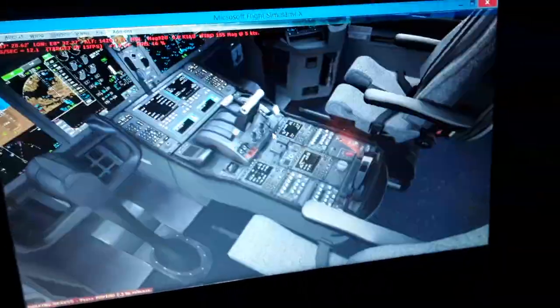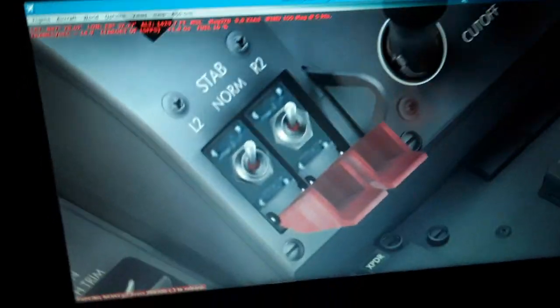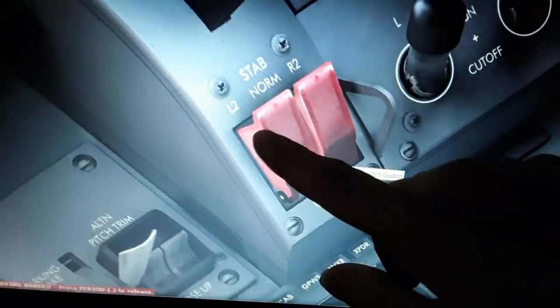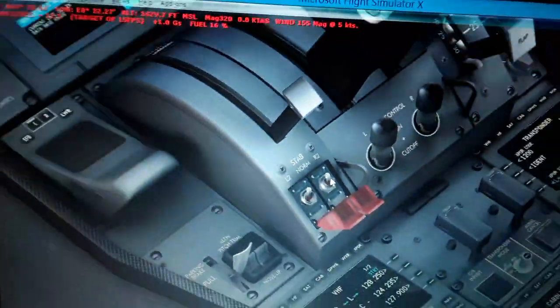It has the flight control computers. So you have a failure from the hydraulics that will affect the horizontal elevator or stabilizer trim. You have to disconnect the auto trim function, the automatic trim. So you will use only the manual trim switch in flight. So you come down here and you open this red guarded switch from normal to cutoff over here. It's for all Boeing 737, 747, 757, 767, 777 and Boeing 787 aircraft, from normal to cutoff.